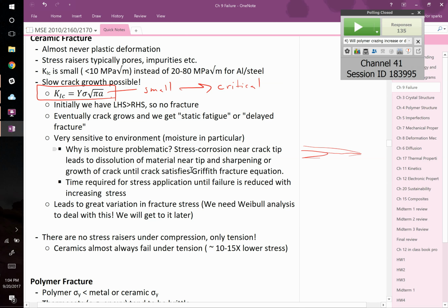You can see this, by the way. If you scribe a piece of quartz tubing and you try and break it, it's pretty hard to break. That stuff's pretty strong. But if you just dip that under water after you scribe it, now you've got water at the tip of that crack, you can break it at least at, you know, half the strength. It's much easier to break.